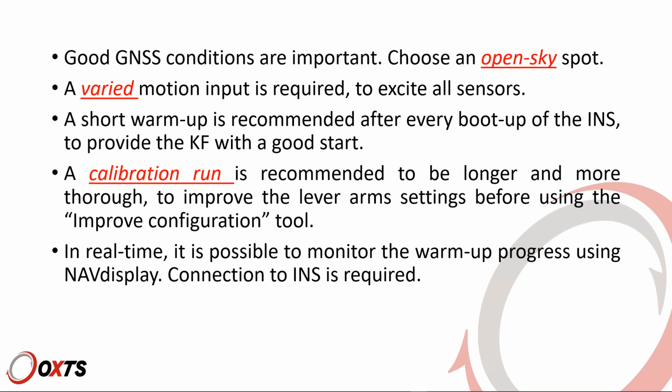You can monitor in real time the progress of your warm-up through our software. Obviously, you will need a connection to the INS, either because you have a wireless connection to it, or you can bring the drone down and connect via Ethernet to the INS, and check how the warm-up is progressing if you want. Otherwise, you can check your data in post-processing.